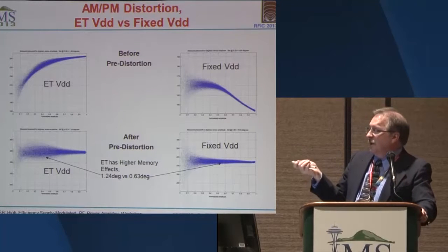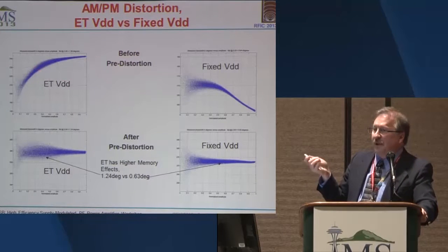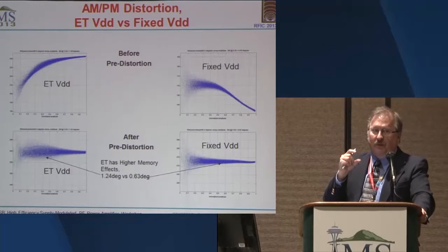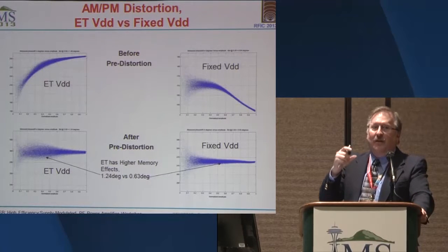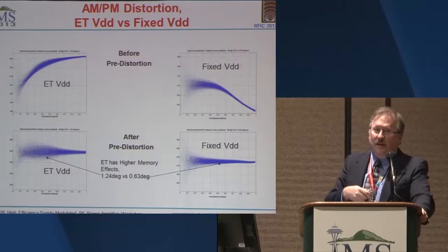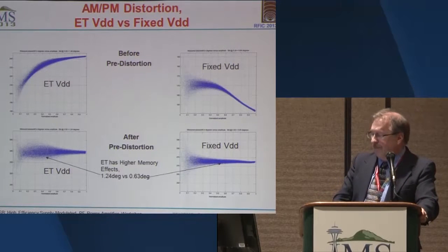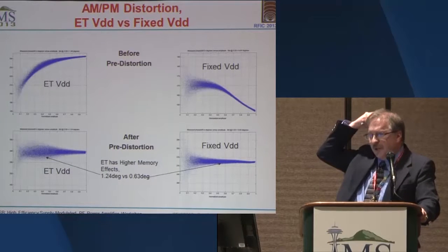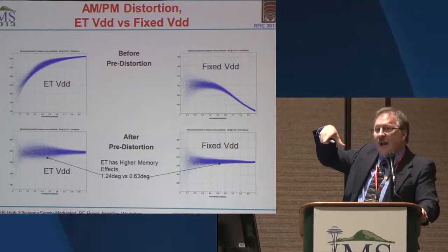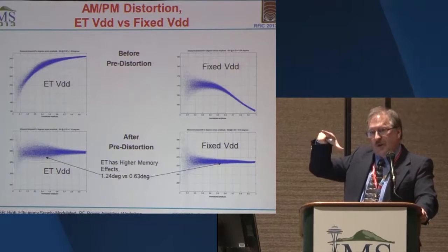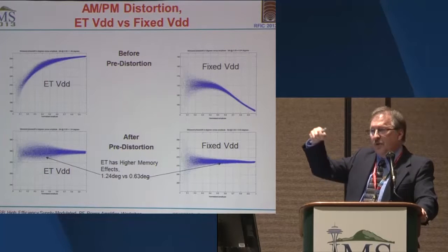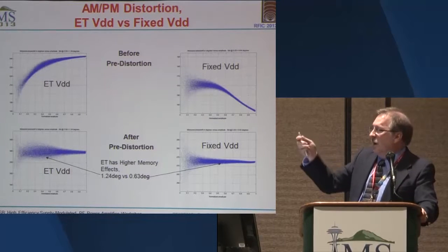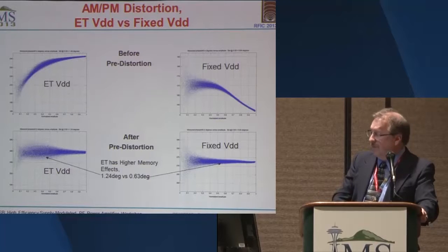But the other thing that kicks in is that the envelope signal will further modulate the AM to PM. It doesn't create an AM to PM directly, but it will modulate it because, a couple of times you've seen the performance surface of V out over V in and VD. There's also a surface that goes with the AM to PM. And so when you start pulling on the VD, you'll get additional splatter on the AM to PM as a result of that.